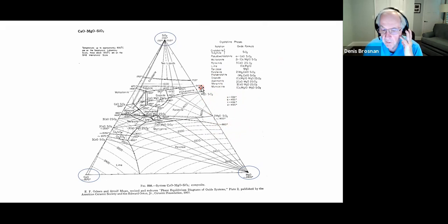Well, I don't want to make this complicated by using these mineral names. We only need to know a couple of them, and we're going to concentrate on forsterite, magnesia, and a compound that's over here called monticellite, CaO.MgO.SiO2, monticellite. So we're really interested in this part of the phase diagram because we're going to pretend that we're making a composition that's at around 90% magnesium oxide.